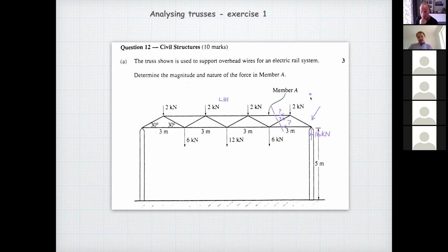And so if I take moments about that point there, that produces a moment, that produces a moment, and that produces a moment. So you're going to end up with x plus y plus z equals whatever, 20. We're going to have 3 unknowns in the equation. So it's silly to take moments about any point, even though the moments about that point equals 0.